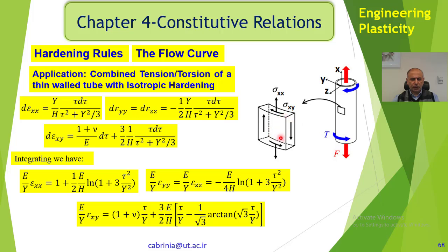These are the stresses and strains, normal and shear, so we have the normal and shear strains as well, and these are the values. These are very useful. In fact, if you load this cylinder by pressurizing, axial load or torsional load, you can get how much plastic deformation you get in the cylinder. It could be used in design problems, and of course this is a simple application. We could have more complicated applications.